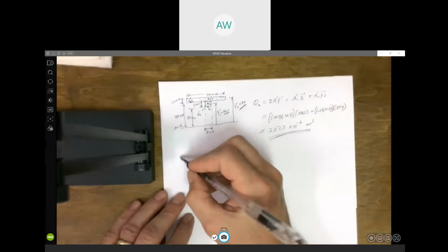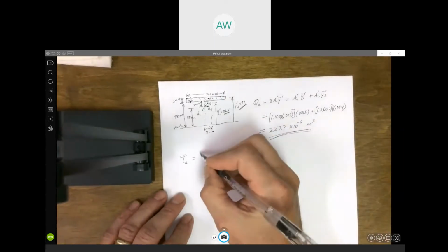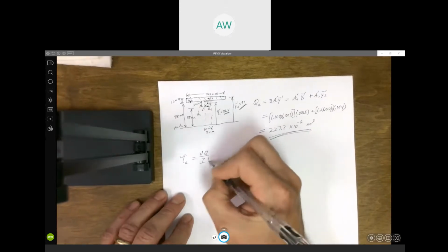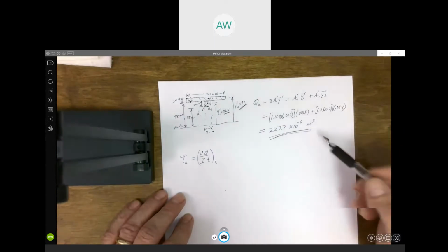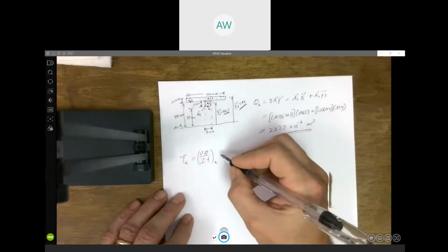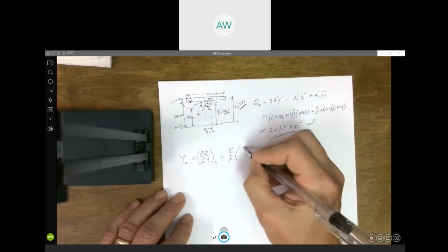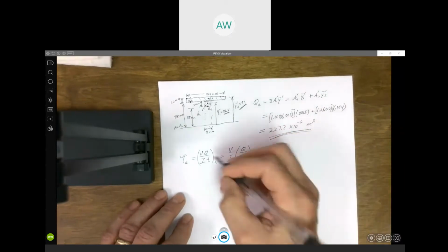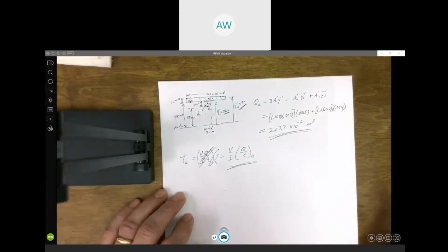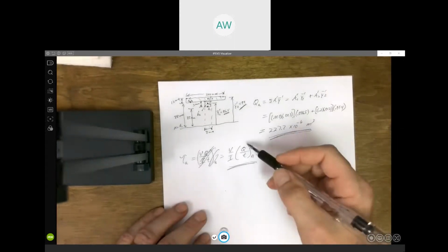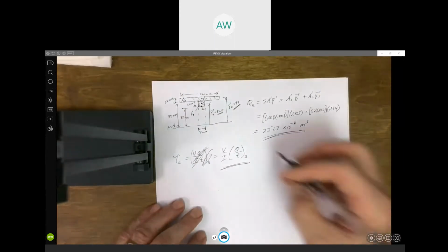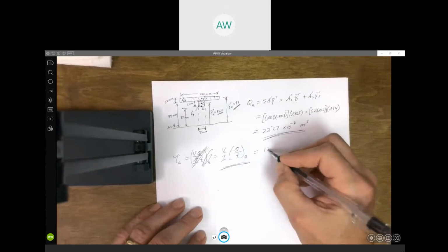Right, so if we're trying to get shear stress at A, again, it's VQ over IT, and we're using values at A. Q and T are the ones that can change. T turned out to be the same, but Q is different. V and I don't change. So we'll just do V over I, Q over T, and A would probably be a better way to write it. Anyway, plug in the values for Q and T. So V was 125 kilonewtons.